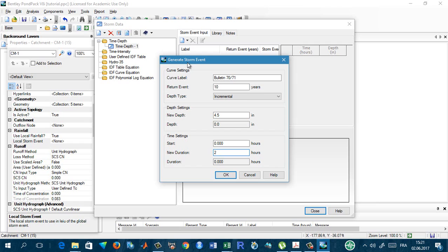They can construct a hydrograph out of those. And a unit hydrograph can be extracted from a hydrograph of a storm event. For example, a 3-hour, 6-hour, 12-hour, or 24-hour storm event. We develop a unit hydrograph, and from that unit hydrograph, we can generate a storm event.